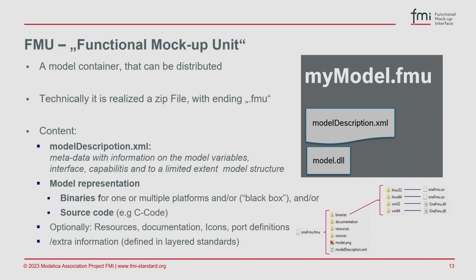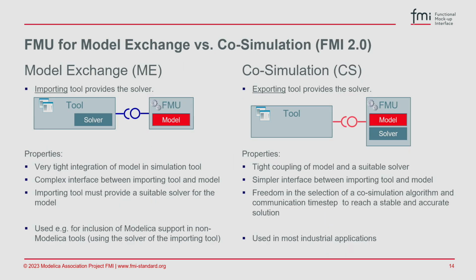And from the communication, in the next slide we will see this, the different FMU kinds, so this model exchange and co-simulation. So at least the communication structure in FMI2, this is really discrete because you have communication points where data is exchanged. In between there can be something continuous, but at least for these co-simulation FMUs, the communication structure is at least discrete, even for continuous variables.